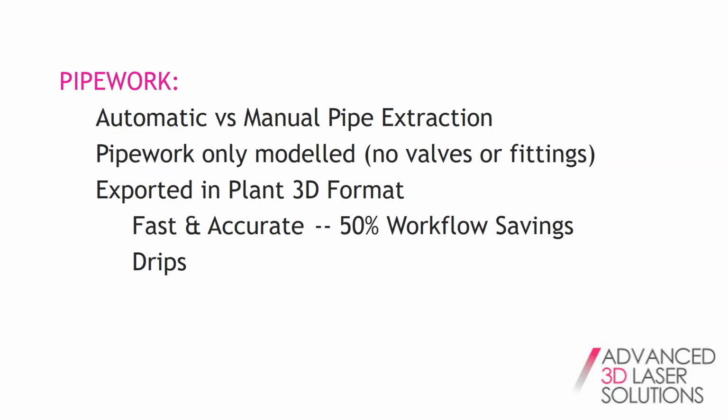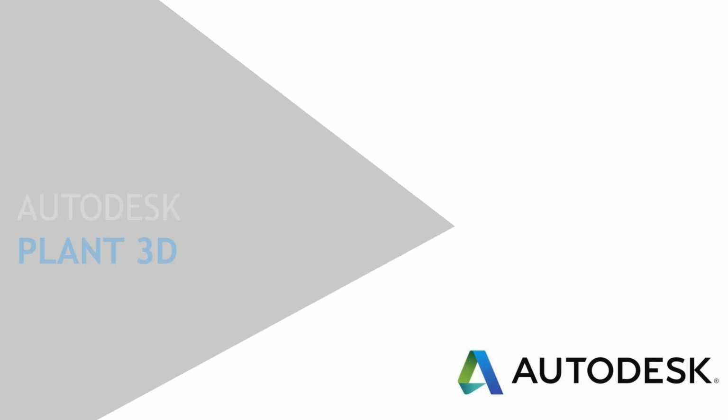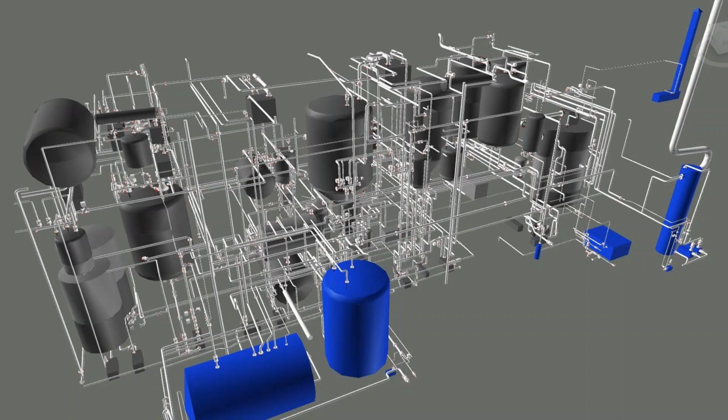So it was 3 times the speed, and it was a lot less stressful. And because it wasn't a direct plugin within AutoCAD, it meant that we could run all the Edgewise registering on one machine. So whilst one guy is finding all the pipe within Edgewise and doing the last little cleanup, the other guy could start setting up the AutoCAD Plant 3D package and getting the project ready, and all the point cloud data ran through Recap and whatnot. So it was a lot quicker.